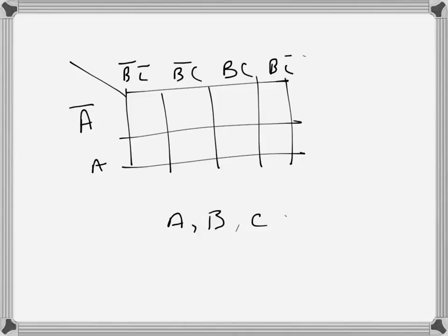So instead of using Boolean algebra, K-maps are used to get the minimized sum of product expression. Now there are some standard methods to minimize from K-maps. First of all, only ones are transferred in the K-map from the truth table. So if we have a truth table and there are a few ones in the output, those ones are placed here.